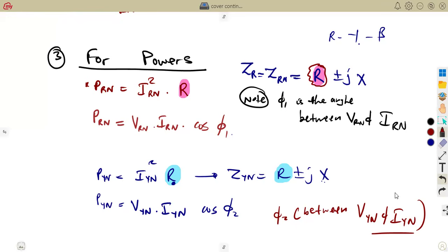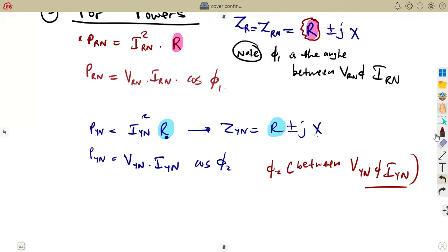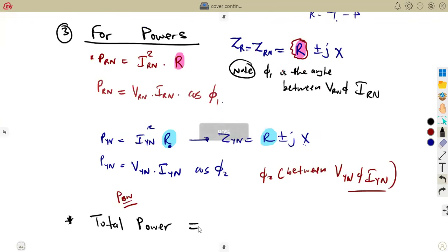So just go through basic calculations of your power, the way that you calculate your power. So that is it for power, guys. You calculate each. Also, you do this one for the blue phase. Then from there, they can even ask you to calculate the total power. Just like what I mentioned before, this power is not the same for unbalanced loads, it is different.